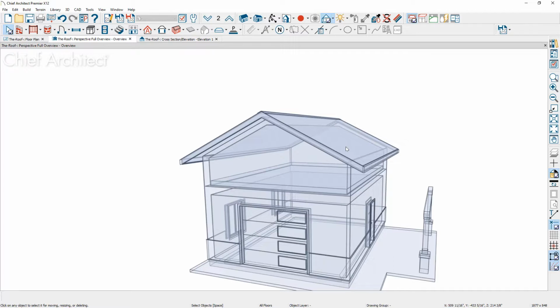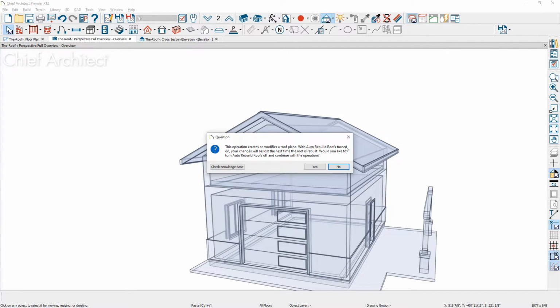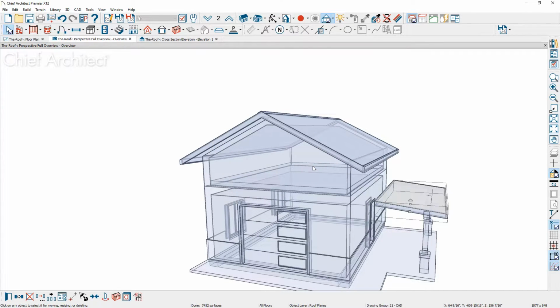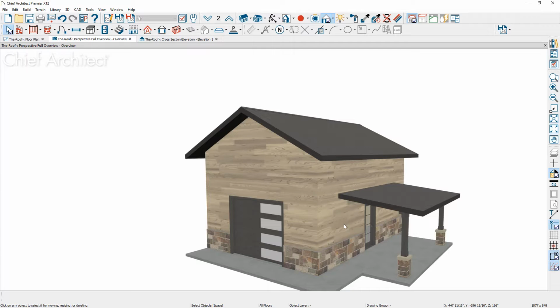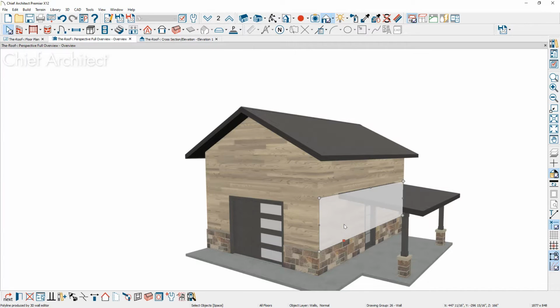Now I'm just going to use the copy paste hold position, turn off the automatic roof. We'll pull that other roof plane in, and then we'll snap that onto the wall, and now I have that roof back on that we had originally deleted. Now the key to making any changes to this roof would be required to be done on the first floor. Let's go ahead and grab the 2 sidewalls.